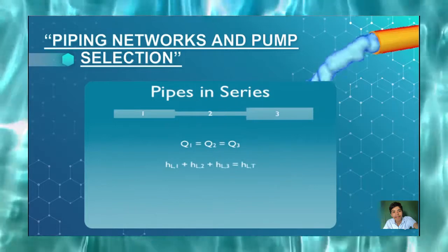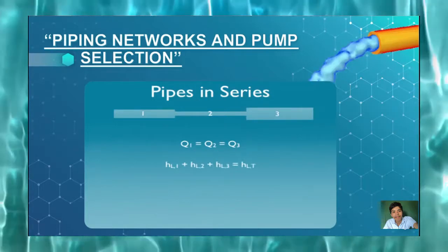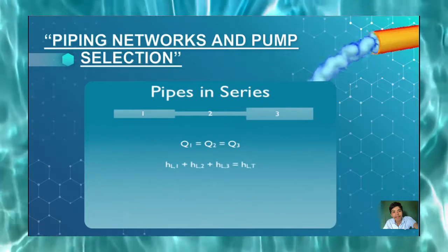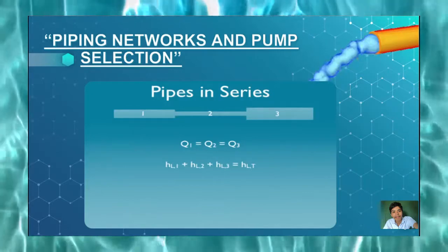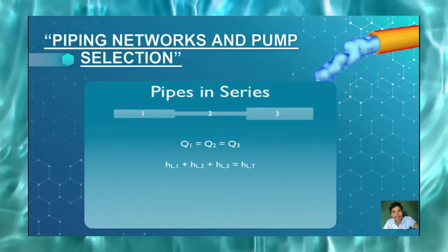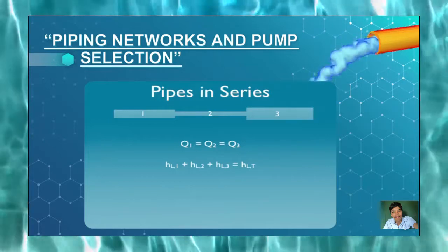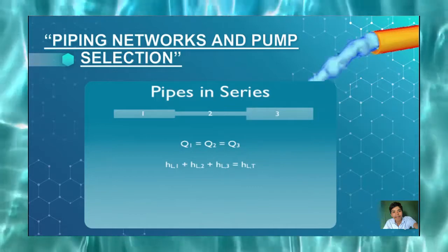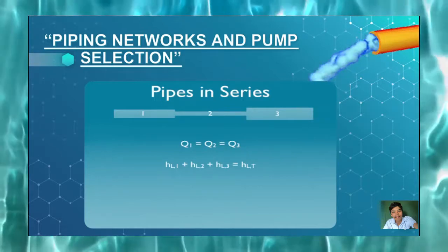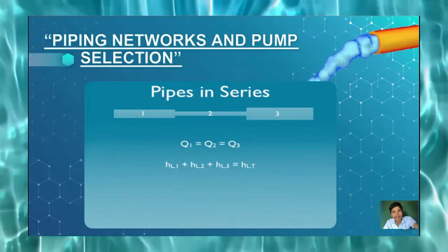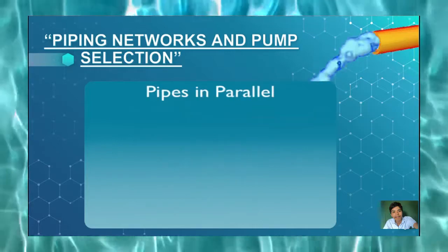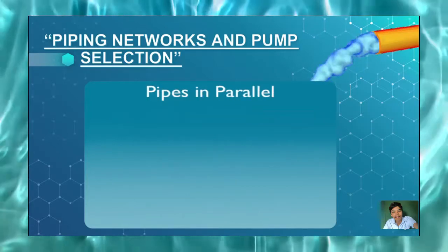The total head loss in this case is equal to the sum of head losses in individual pipes in the system, including the minor losses. The expansion or contraction losses at connections are considered to belong to the smaller diameter pipe since the expansion and contraction loss coefficients are defined on the basis of the average velocity in the smaller diameter pipe.